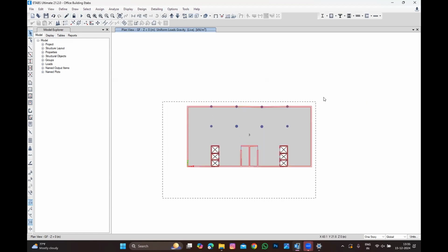Okay. Select this ground floor. Make sure every time when you do selection, you click CLR. When you click CLR, if it is hidden, then nothing has been selected. Because sometimes by mistake, a point or a column has been selected. For example, I have selected one column, so CLR is on. So just make sure CLR is hidden and select this ground floor.